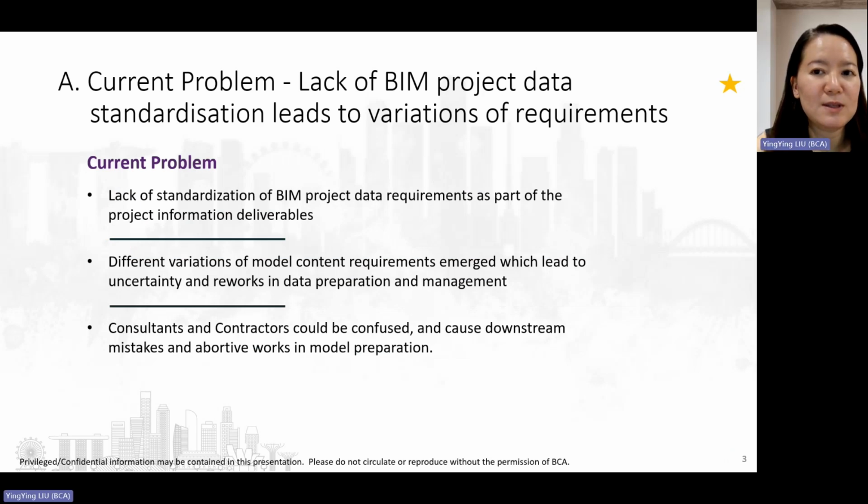Model Content Requirements, or MCR, was developed because there is a lack of standardized information requirements for BIM projects. This resulted in various versions of project deliverables, leading to misunderstandings and errors in information production. MCR aims to address this issue by establishing clear definitions and eliminating discrepancies for model objects and properties. The goal of MCR is to allow industry practitioners to prepare models based on a standard set of requirements and refer to the same coordinated BIM model as a single source of truth.